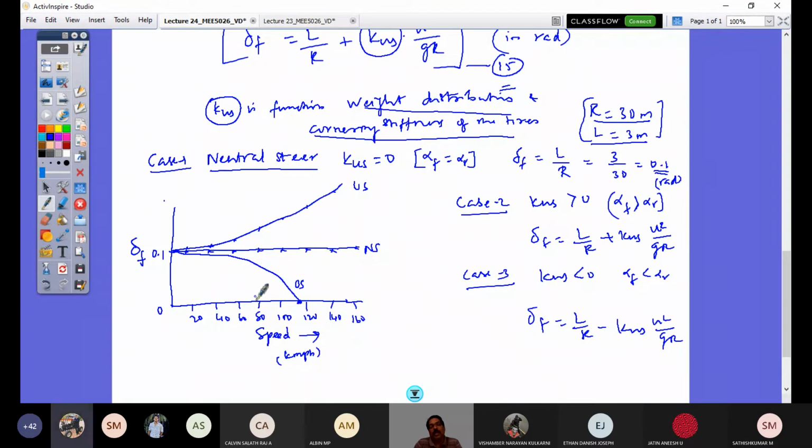So what do you mean by that? Do you follow that? Yes. So the rear of the vehicle leaves the traction. That is the point at which the yaw motion continues, but we do not have to give the steering angle. You cannot have the steering control, that is out of control.